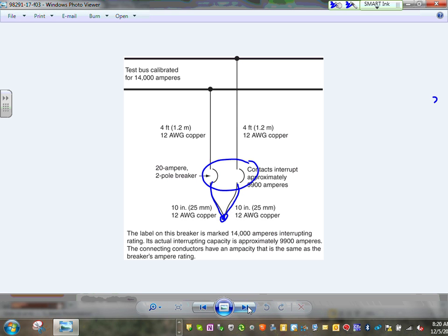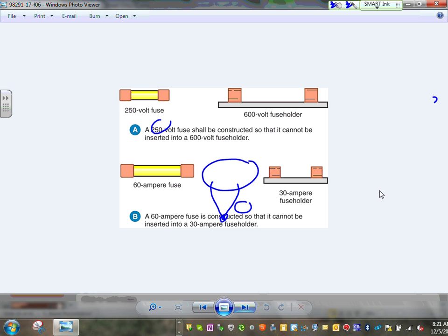If it can't, then look, you take the 4 feet from the service, put these conductors in, and tie them together here. If the circuit breaker can handle this one, you're good. That's how they rate the circuit breakers when you say 10,000 amp interrupting rating. UL does that all the time. Okay, any comments, guys?